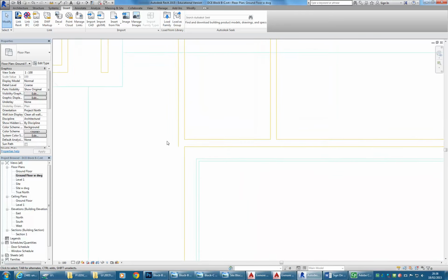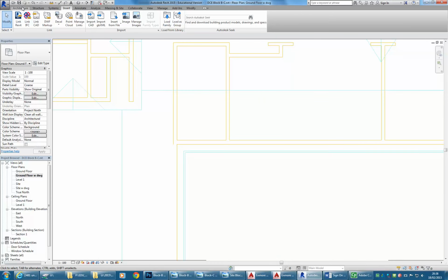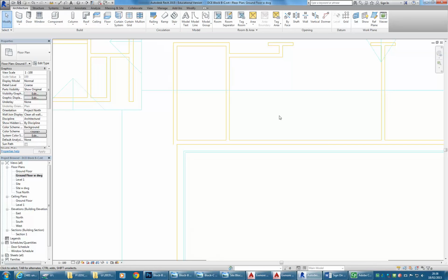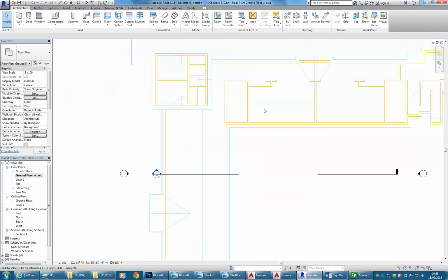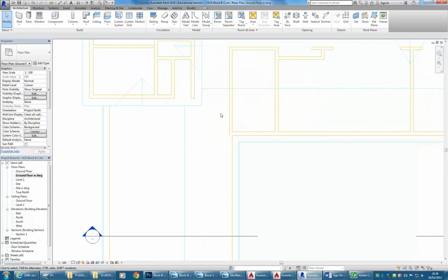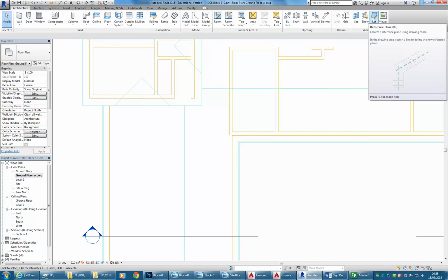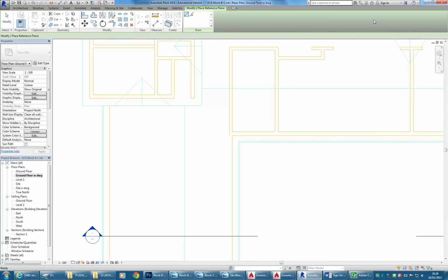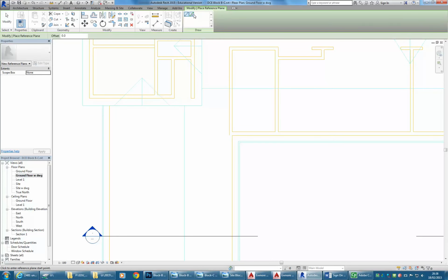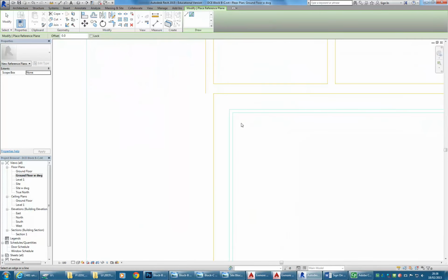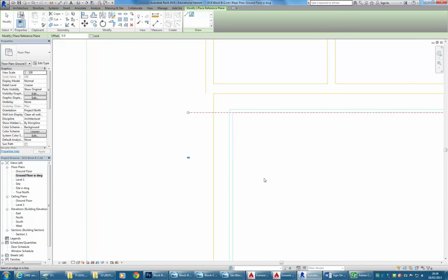Okay, so I've got there a point that I can use, a corner point that I can use and correlate between the different views. Right, so there are lots of really good tools in Revit for setting datum points, but they get a bit complicated, so I'm going to keep it simple and just use reference planes. And so there I'll use a reference plane or ref plane on the architecture tab, and then pick lines, and I'm going to pick the outside edge of my gutter, stretch it across so it's a bit longer, and then the other outside edge of the gutter coming up. Stretch it up.